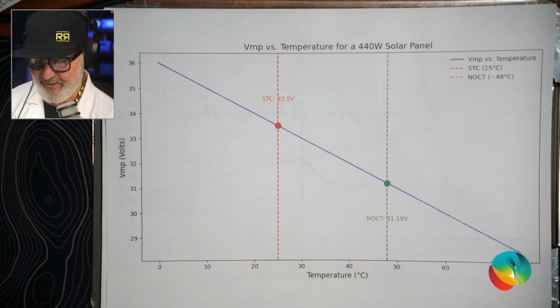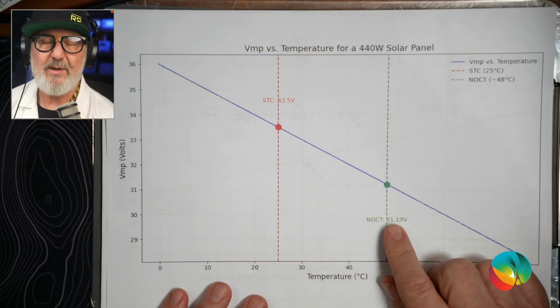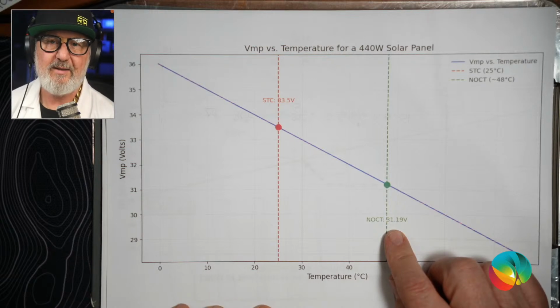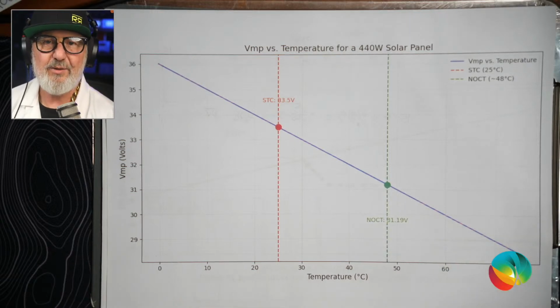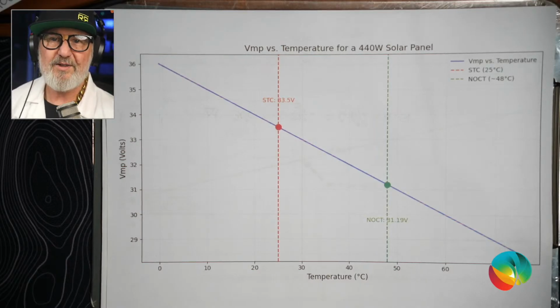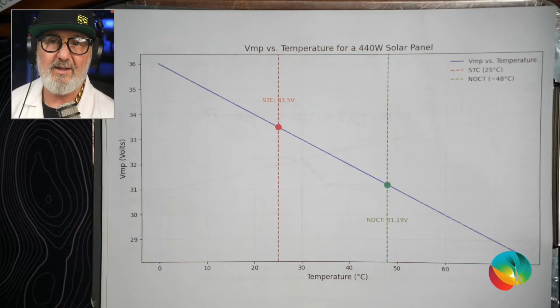Why do I say that? Well, instead of using 1,000 watts per square metre to test the panels, for NOCT they use 800 watts per square metre. That's because in the northern hemisphere there are more atmospheric particles and pollution basically, and irradiance is suppressed more than it is in the southern hemisphere. So woohoo for us in the southern hemisphere, we get higher solar radiation.